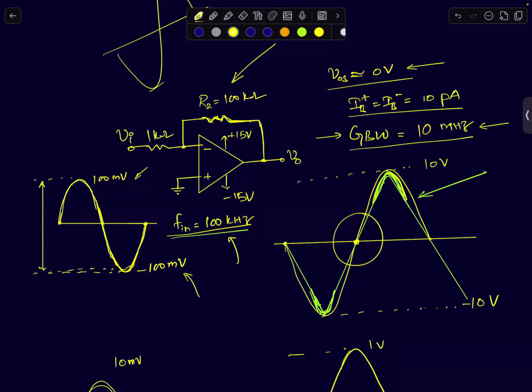Okay. So let me, for example, in this circuit, assume the gain bandwidth product is 100 megahertz. I'll explain later why I took 100 megahertz. The feedback factor is 1/100 for this case. In the next class it will become much clearer, but let's assume it is 100 megahertz instead of 10 meg. It is still much higher than 100 kilohertz. I just took this 100 megahertz to avoid any practical problems, so let's ignore that.